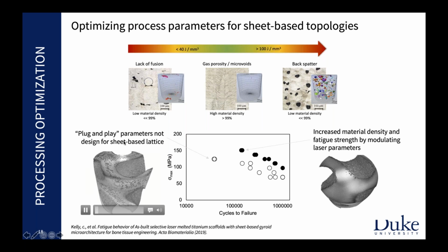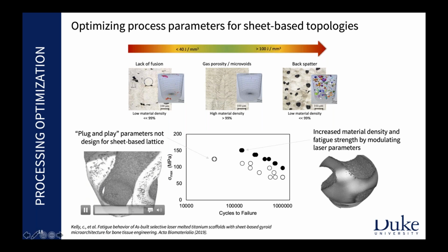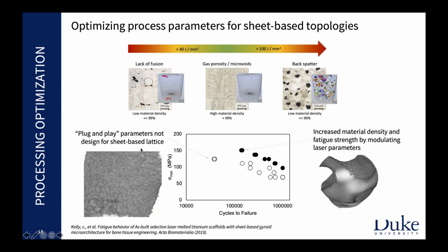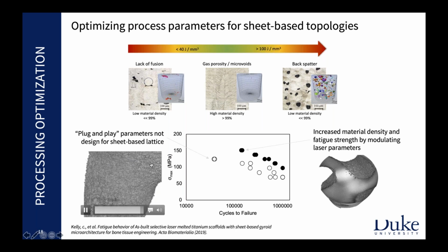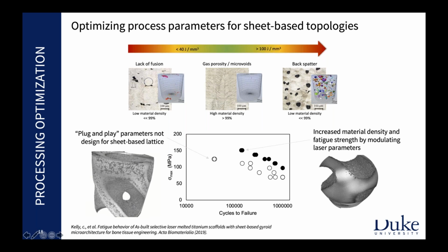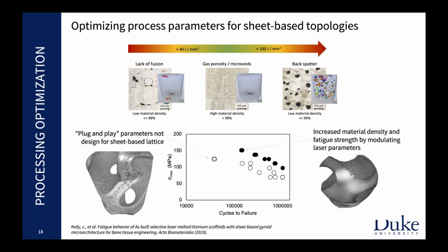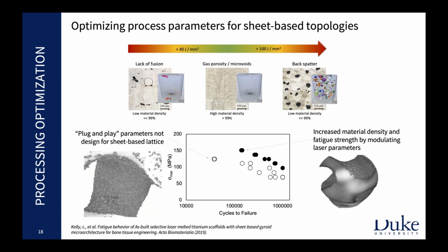This is a nano CT, computed tomography, of a porous structure that's printed. And all those little pores in there, what we found is that the parameters that the manufacturer gave us were terrible. So we ended up in a situation where all these structures, and you can kind of see the powder there, had a bunch of pores that we didn't plan on having within the walls. And so we ended up having to play around with the parameters of the laser, and understanding how we use laser power, scan speed and the dwell time to really print more of a solid structure.